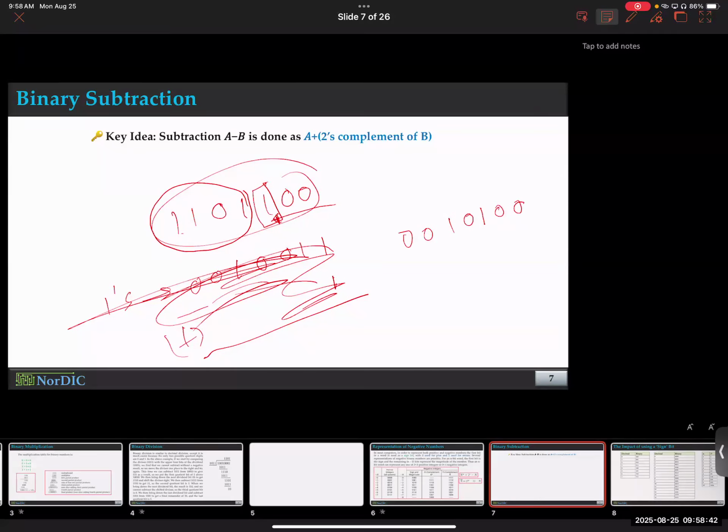Right? It just flips the bits. So imagine you have a stream of binary bits. You take an inverter, which is a logic gate, the simplest possible gate ever. You might be wondering, why would somebody use an inverter? Maybe because of this. You just take a number, you invert it, you get one's complement. And you add 1 to it, you get 2's complement and something like that.